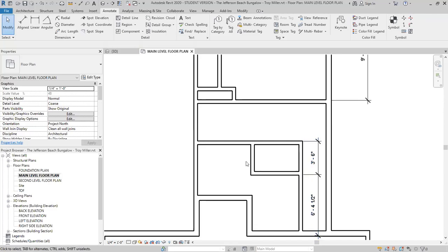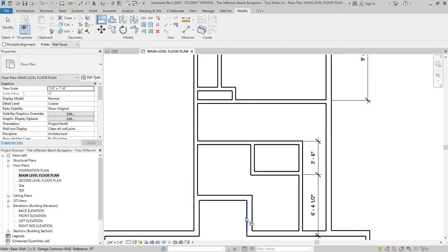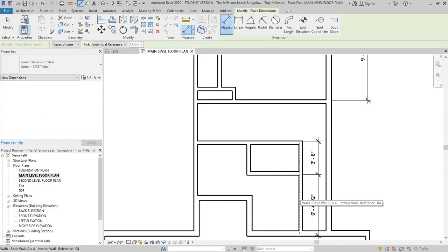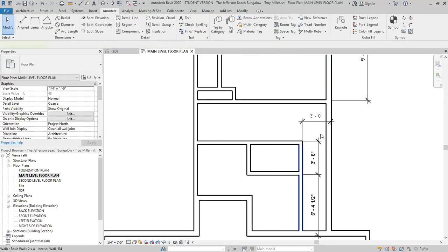The other thing I'm looking at really quickly is, where does this wall go? It appears to me, looks like we have a little 6-inch wall that we need to create right here, but until we do that, it appears to me I can use that modify command, because the outside plane of the wall here lines up with the outside plane of the wall right there. Now it looks like I also threw another dimension here. It appears to me that this wall in relation to that wall is not located correctly, so I'll throw that dimension in.